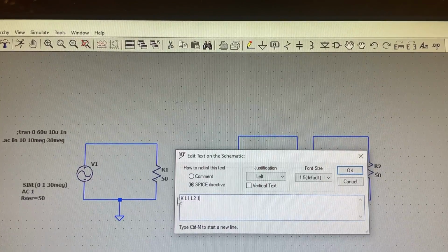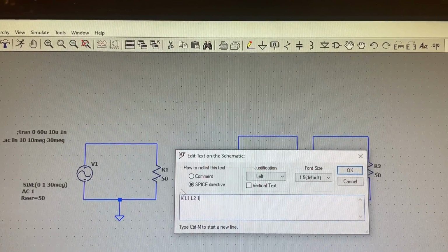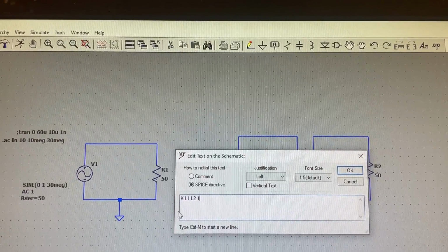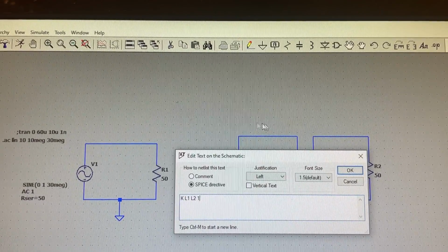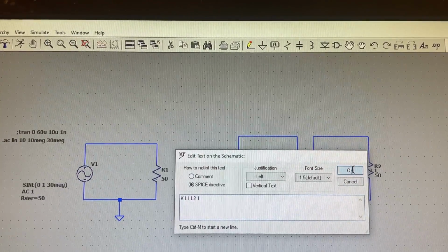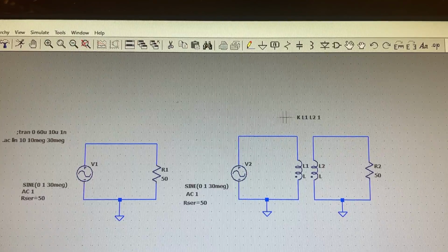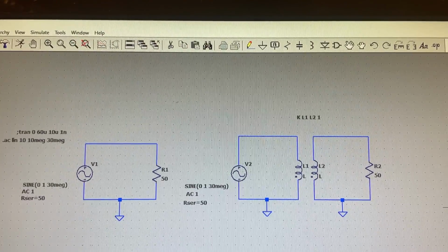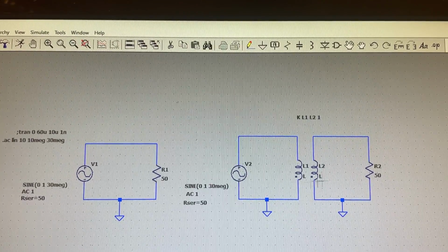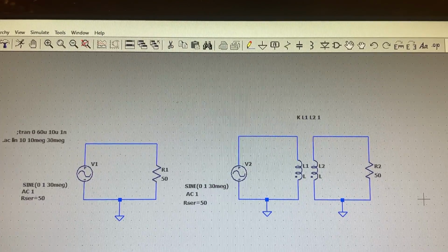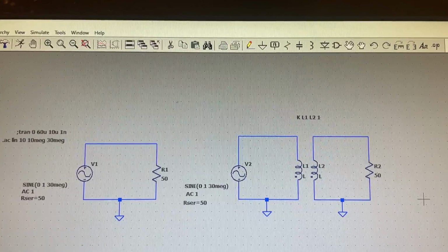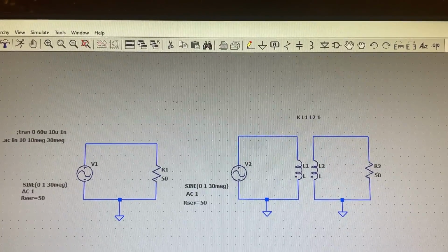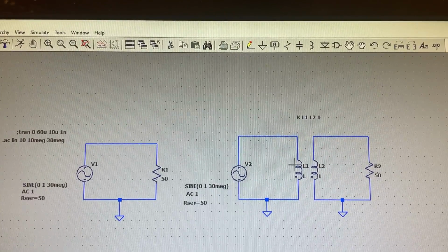We're going to talk about how to actually measure the leakage in your transformers and measure the K value. And then you can enter the real value right on your schematic. So we click OK, and that's basically a transformer now. You can see the phase dots on the bottom here that show they're coupled. So now we have to define what the value is here for inductance.